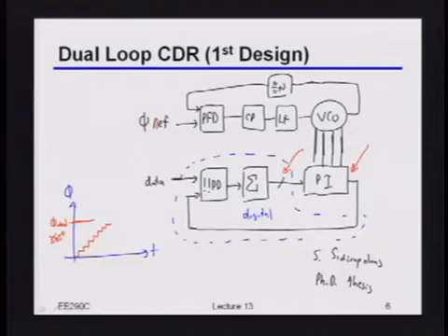On the other hand, I still, of course, have to recover the clock somehow from my data. So what I do for that is I take the clock generated by my PLL, and as we'll see maybe this lecture, if not, then next time, you often tend to grab multiple phases from that clock, from that ring oscillator. Then you use those multiple phases to generate a controllable delay through what's known as a phase interpolator. So for now, just think of a phase interpolator as a way of generating an arbitrary phase clock at the output.